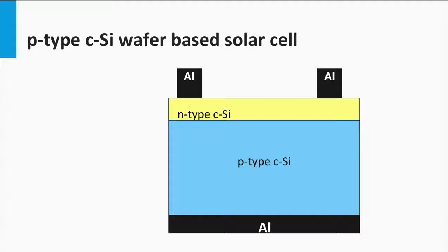At the PN junction, the light-excited minority charge carriers are separated. The minority electrons in the P layer drift to the N layer. These electrons have to be collected. Since the silicon N emitter is not conductive enough, we have to use the more conductive metal contacts. The metal contacts are placed on top of the emitter layer. Here the metal contacts are made of the cheap metal aluminum. This means that the electrons have to diffuse laterally through the emitter layer to the contact to be collected.